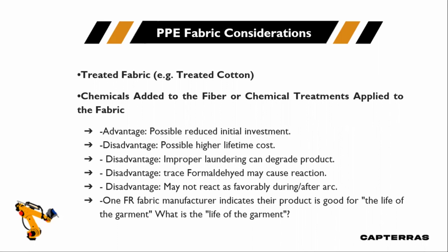Let's discuss some points. Advantage: possible reduced initial investment. Disadvantage: possible higher lifetime cost. Disadvantage: improper laundering can degrade the product. Disadvantage: trace formaldehyde may cause reaction. Disadvantage: may not react as favorably during an arc. And finally, one FR fabric manufacturer indicates their product is good for the life of the garment. What is the life of the garment?